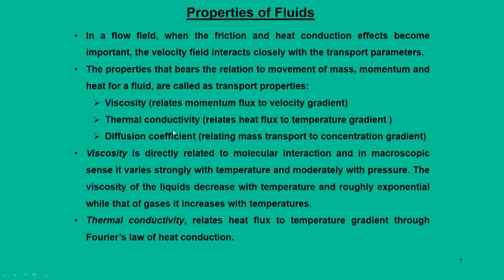Other properties of the fluids are transport properties, which essentially mean the movement of mass, momentum and heat in a fluid; if these properties get transported during the motion, we call them transport properties. The transport properties are mainly viscosity, which relates momentum flux to velocity gradient.